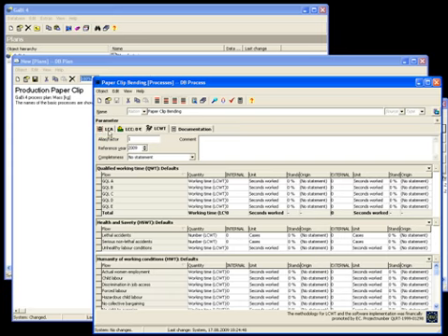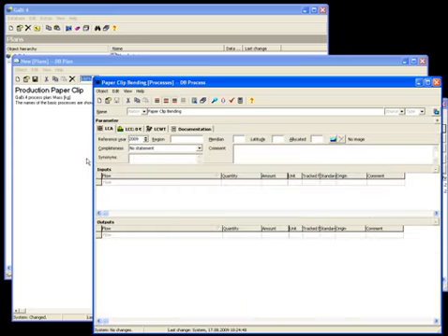Flow information can be added to processes by defining input and output flows in much the same way that a simple input-output diagram is done. A huge variety of material and energy flows that are common in industry are already integrated in the GaBi databases. A flow of steel wire, for example, is found automatically and can be entered in the input line. This allows for the steel wire production process to be connected to the paperclip bending process later on.